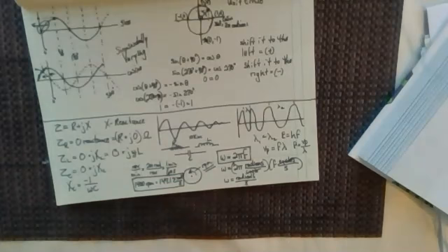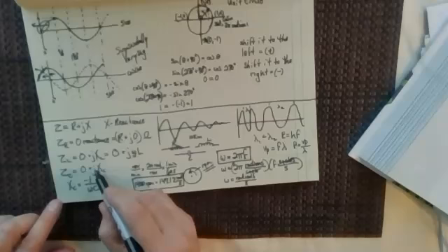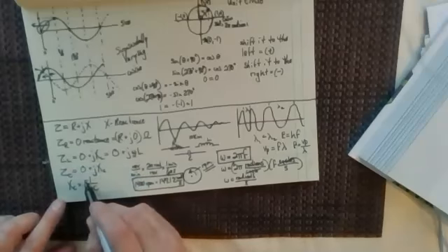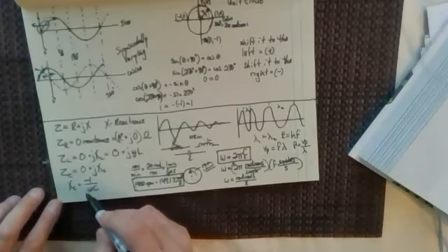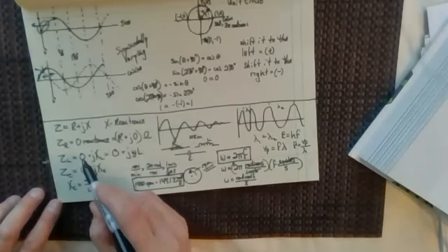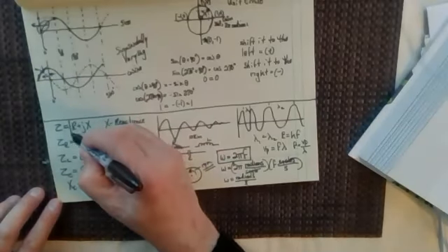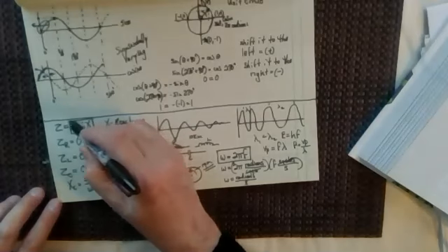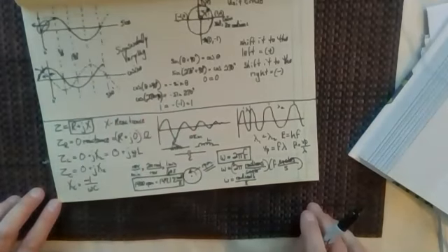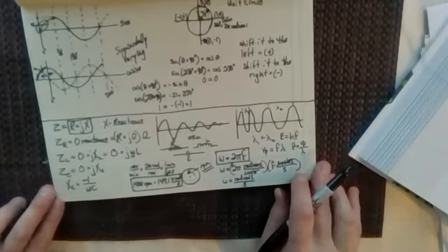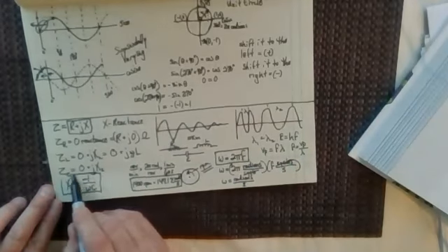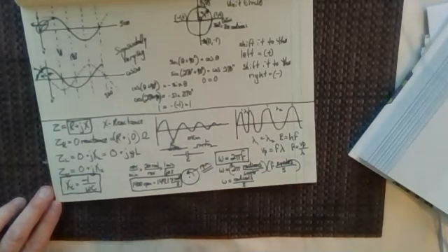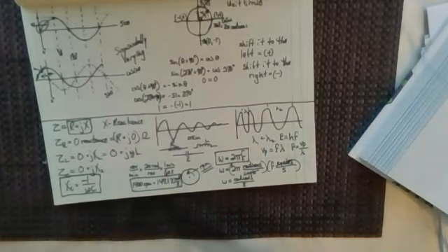But I like to teach it like this, because really this is j, plus, and you can see the plus, but then you can see the minus. And the minus is really in the reactance, I believe, rather than changing this. We should always keep this the same. The definition of impedance is R plus jX. So we should always have that plus there, and then we should keep the minus in the reactance, 1 over omega c. And now we'll get into that.